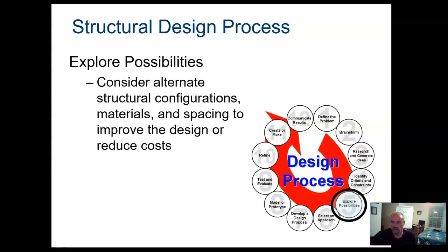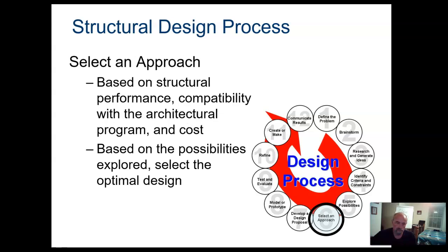Once the load to each structural member has been established, options to resist the loads can be explored. For instance, you may want to explore the possibility of using both hollow core precast panels and composite concrete floors. If structural steel floor framing is to be used, you may want to consider both open web steel joists and structural I-beams. There is opportunity to adjust spacing of structural members, such as floor joists and columns, if necessary, to improve the design and to reduce the cost. The design must be selected for every structural element in the structural system.